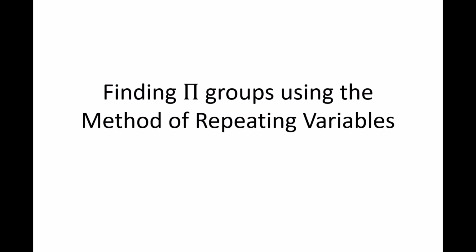In this lesson, we will discuss how to find pi groups using the method of repeating variables. In dimensional analysis, there are a few methods for finding the dimensionless groupings of variables called pi groups. The method of repeating variables allows us to find pi groups in a systematic manner, and it is a safe, reliable method for students who are just beginning to learn about dimensional analysis.